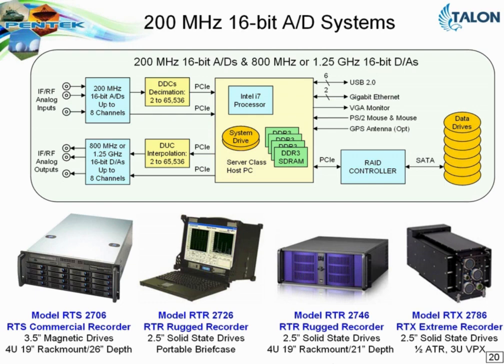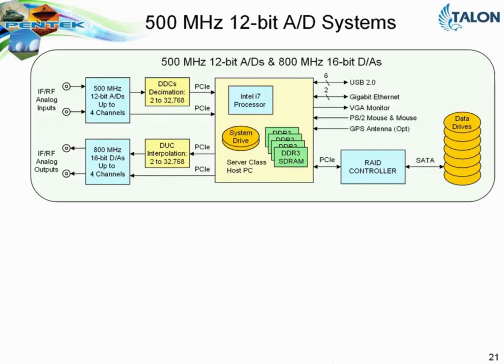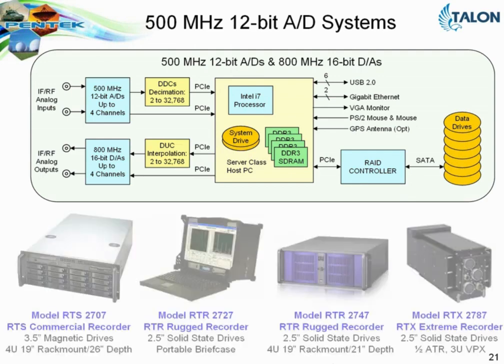We have also recently announced a 8-channel serial FPDP recorder. Serial FPDP, also known as VITA 17.1, provides up to 8 links of either copper or optical serial FPDP traffic. These are excellent links between systems. They can go to distances as long as 10 kilometers with the optical single-mode fiber. And each of those links can operate at least 247 megabytes per second, so we can have up to 8 of those.